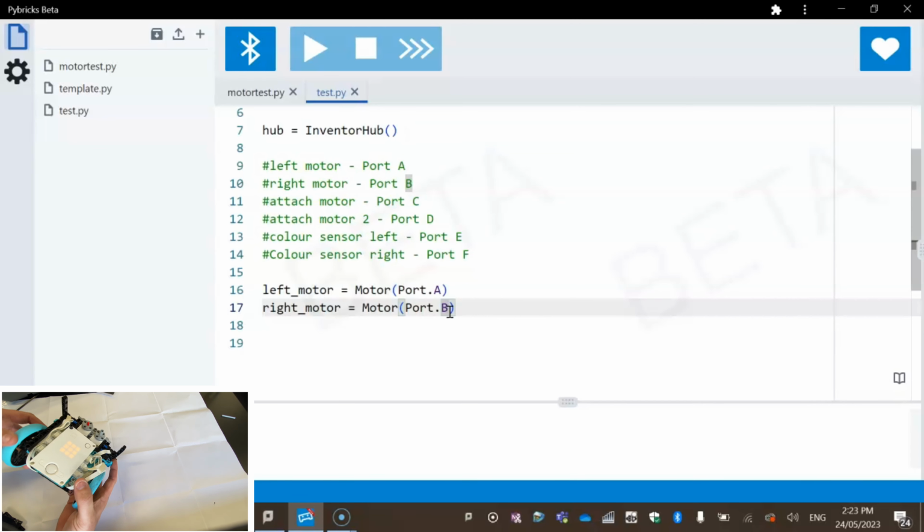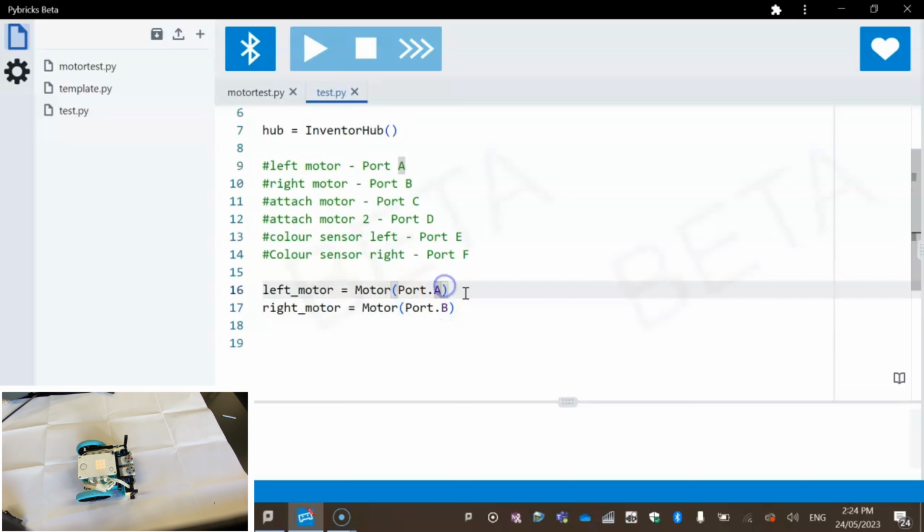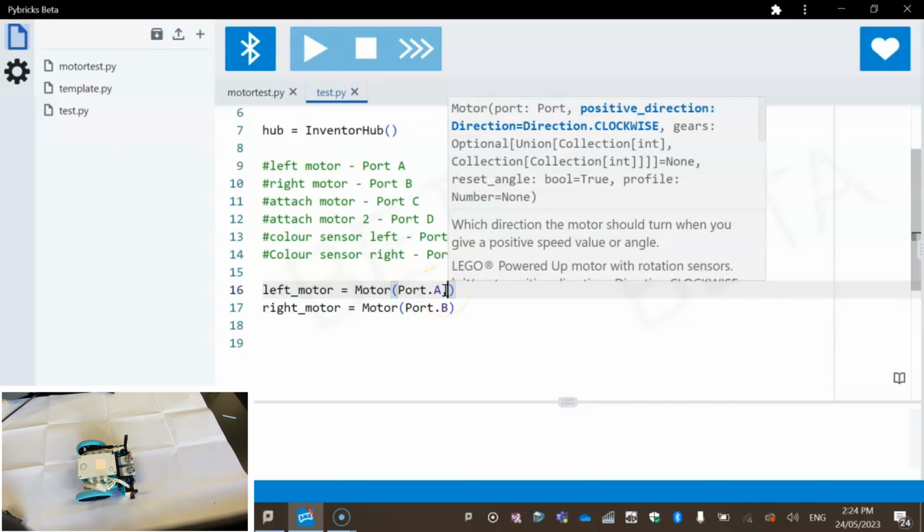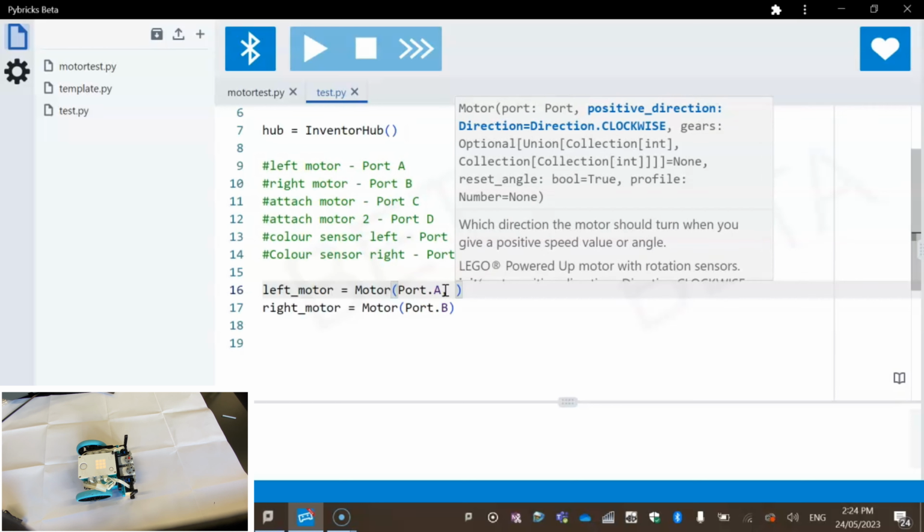Okay, so when we talk to them, and we talk to them in separate sentences here, because we don't have the benefit of using the pink blocks, but we will later on. So what we need to do in this part where it says port B is we are actually going to find out which one is actually going to drive counterclockwise. So I'm going to say it's actually this first one here, so it'll be the left motor, and I'm going to say it is.